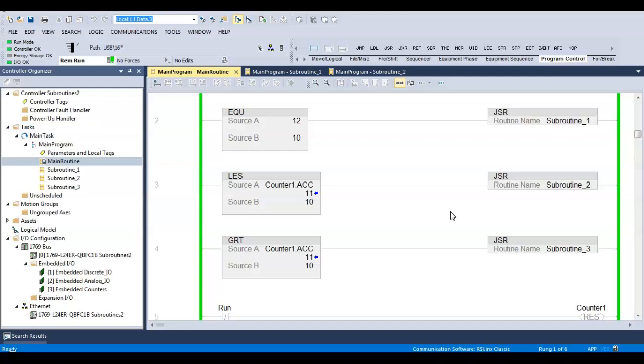Okay, but why? So that's exactly what we're supposed to see here. Why? Well, the subroutine's not running anymore. The outputs are not being updated. If the outputs are not being updated, they maintain their last position. So what I'm saying is when you do subroutines, you better take care of your outputs before you leave the subroutine. Because if you don't, if they were on when you ran it, they're going to be on forever if you don't run it again, right?